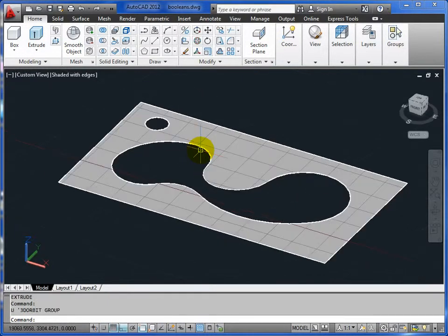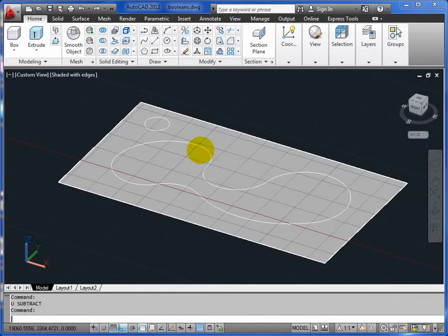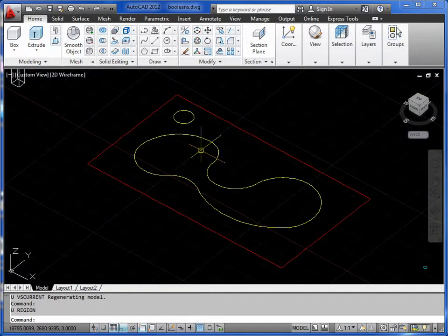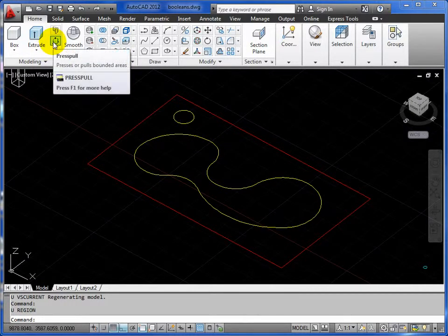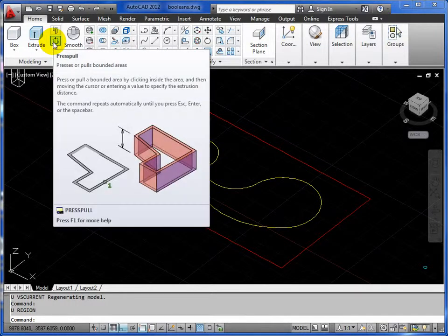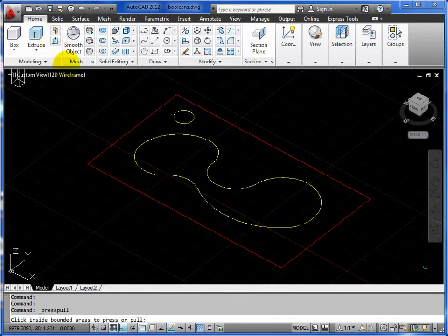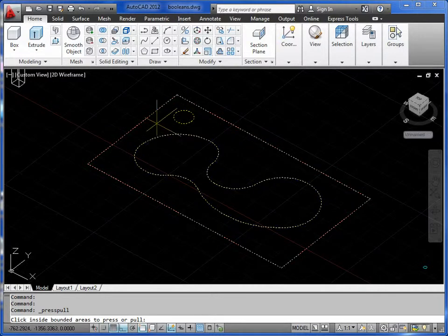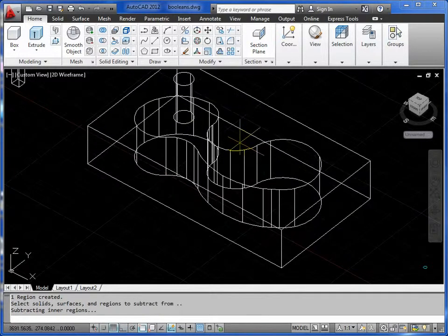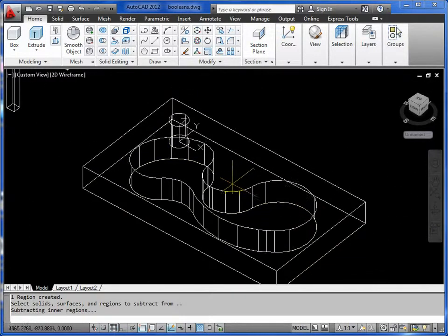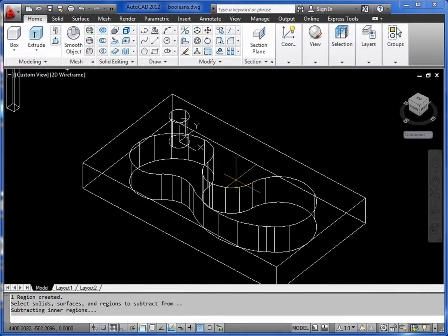I'm just going to drop back a few clicks here, just show you another feature of the software that's arrived with the 2012 version, and that's called push-pull modeling. I can't really see myself using it too much, but it's there, and it's good to know that you can do it. So, okay, go press pull. It's called. Okay, and watch what happens with the cursor. It's highlighting the different shapes that could be brought up. So if I leave my cursor hanging in here in the gap between the shapes, you see how it's creating the solid in that manner.